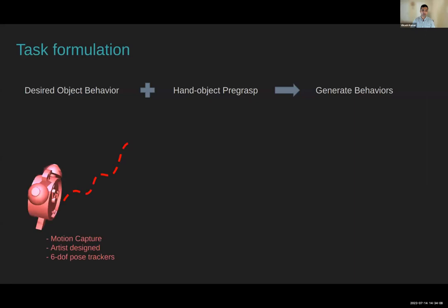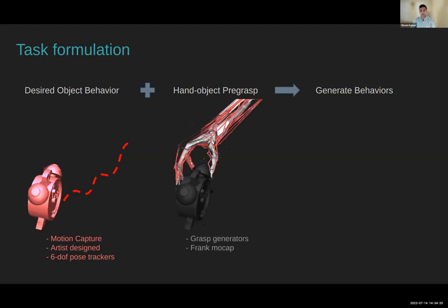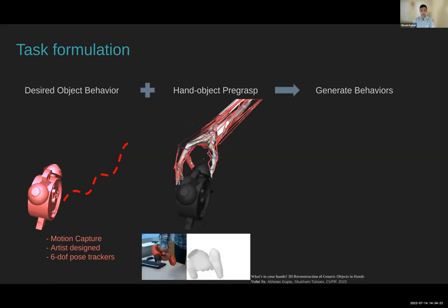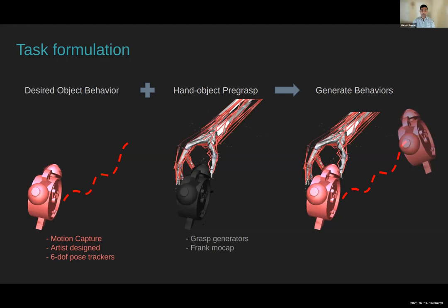And finally, what the whole thing looks like is you take any object and specify the trajectory the object should be taking. So the only specification is based on object trajectory. Then you can hit it with these affordance models, and they basically predict things like, hey, what should happen with this particular object? And you get a posture like this, and then you generate behavior. These two ingredients are very generic to any task, and there is no reward function tuning that is allowed. This is a standard reinforcement learning PPO algorithm, but it's just specified in these two unique ways.